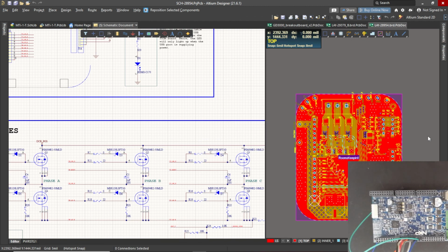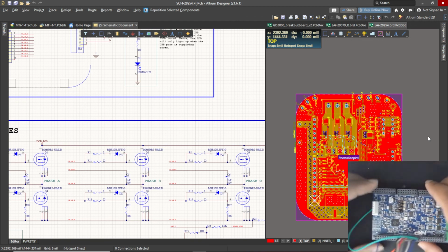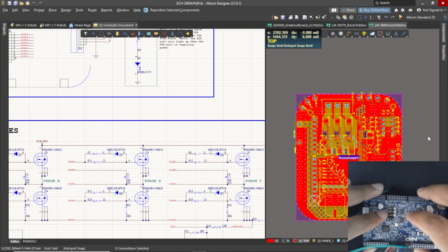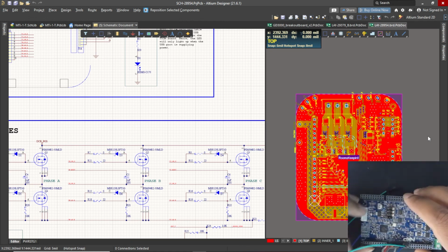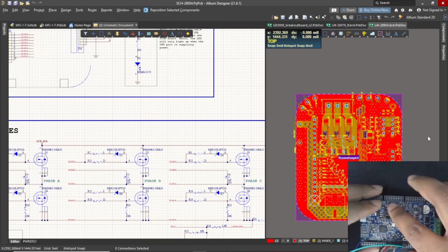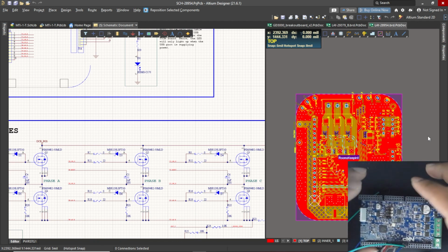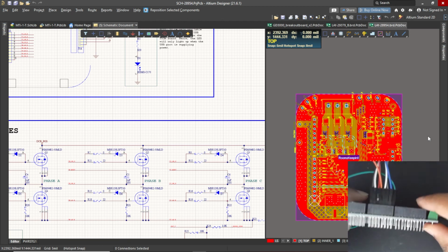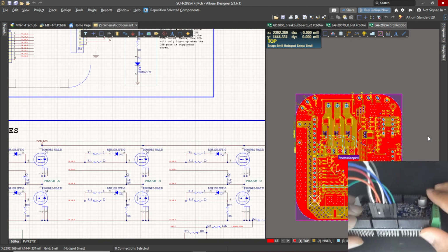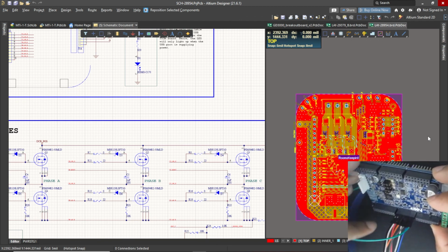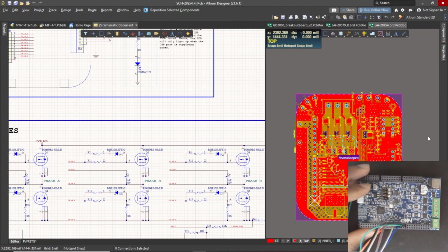So I'm moving a little slowly. It's primarily because there's a gap in my knowledge, and I want to address it in the best way possible. So the next step is to make this work and probe this really well. Another way is to simulate some of my boards using PSpice, figure out whether these connections work or not, and try to model this board as closely as possible so that I can simulate before fabricating. That's another step in the direction. So I'm reading a little bit more about how I can simulate these boards using 2D field solvers and 3D field solvers, and better understand my signal integrity issues.